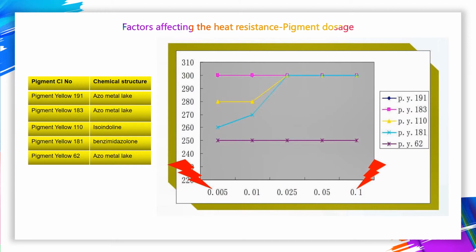Heat resistance under different concentrations is very important for plastic colorists in their daily work. It is not only light tones that require a very low concentration of colorant; when doing color matching, maybe the concentration of colorant is lower. So we can only use the colorants whose heat resistance does not decline with the decrease of concentration.